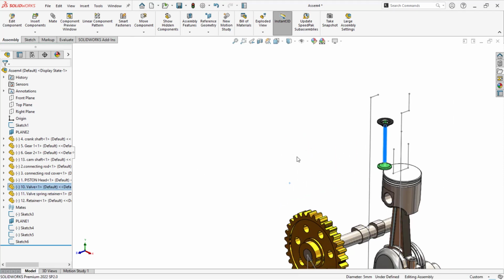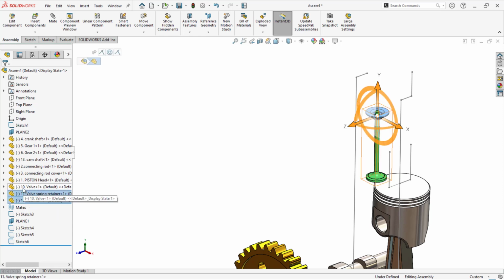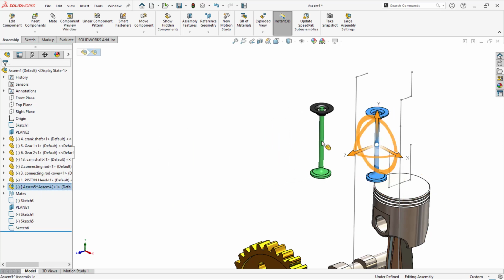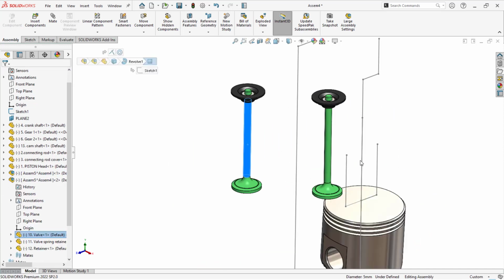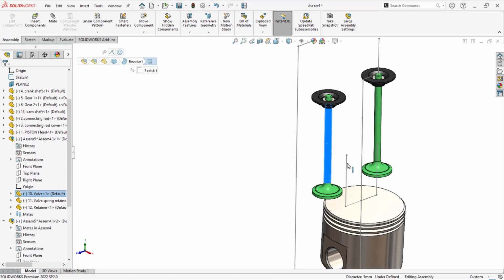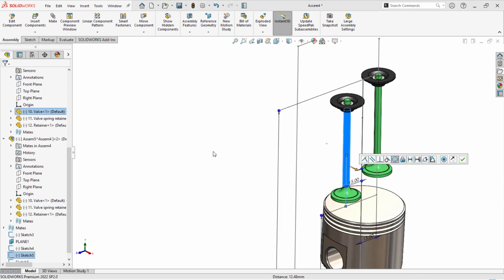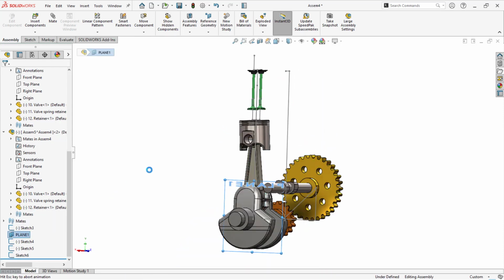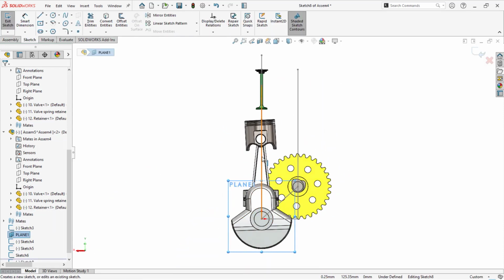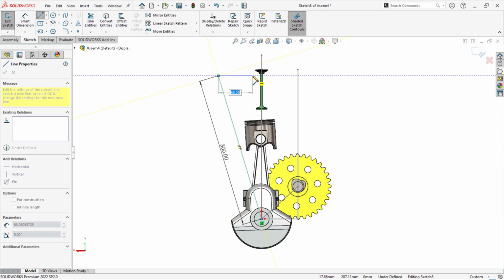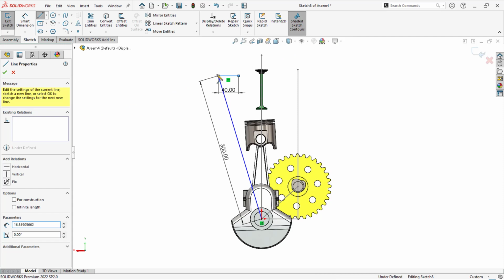So I need one more assembly of this, so what I'll do is I'll just form a new sub assembly here. This is again a shortcut, so hold the control, drag and drop it. Now these two concentric, again these two concentric, isn't it? Yep, so this much is ready. Next thing is to add the sketch. As I said, this is a straight line. I'll refer it up to 300 and I'll draw a line up to 40.